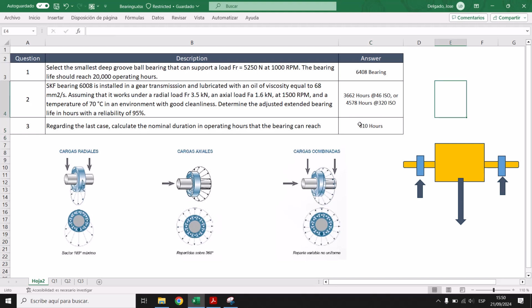Look at the difference. That's the reason why in maintenance there's always something that you should know. Let's lubricate in this. Maybe you use a bearing type of 2Z or 2RS. Both of these don't need lubrication because they are covered. The lubrication of that bearing is for its entire life. But this is an example.